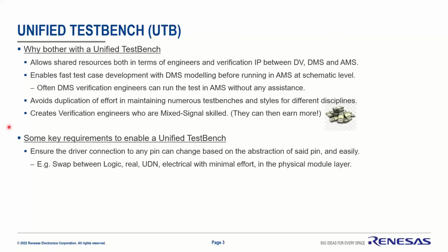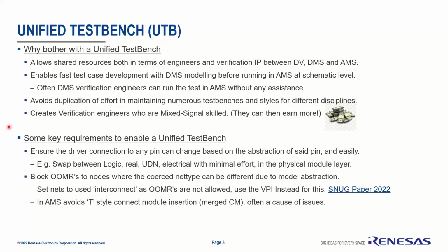What I mean by that is, if I've got a DUT pin that is a logic, but then I change the abstraction of that DUT by a model change, so it's no longer logic, it's a real or a UDN or electrical, I want to be able to change the driver to speak to it without having to regenerate a completely different test bench. And that's one of the key things that I pushed into UVM-AMS.